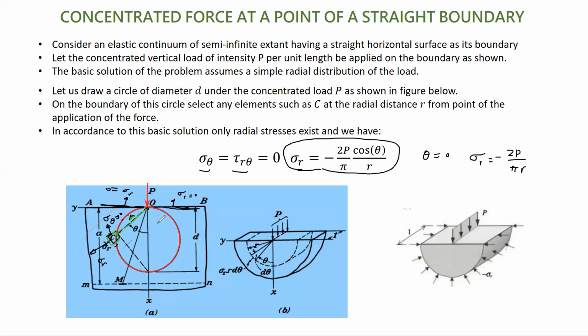That's what we expect. Just under point O, the stress should be infinity, and anywhere away from that is defined from this equation. And you can see as you increase the value of the radial direction, the stress decreases. So as we go further down onto this plate, the stress through the thickness of this plate, the effect of the concentrated load would diminish.